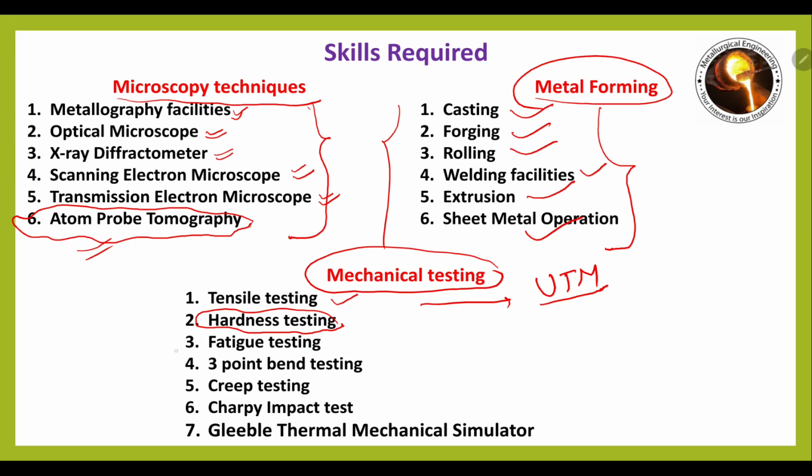And then we have the most important thing, fatigue testing, because most engineering materials fail due to fatigue loading. You can say 90% of engineering materials fail due to fatigue. So we need to understand how we can increase the fatigue life of the existing material, or if you are designing a new material, you can calculate the fatigue life using fatigue testing.